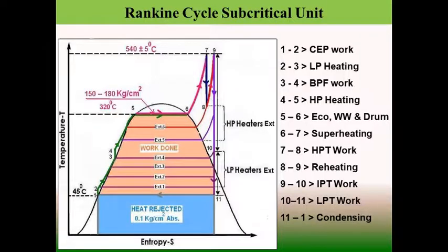So naturally we find that though in this cycle both point 5 and 6 are present in the boiler drum, point 5 represents the saturated water and point 6 represents saturated steam, and in between the passage, that is basically representing the addition of latent heat within the water wall tubes.